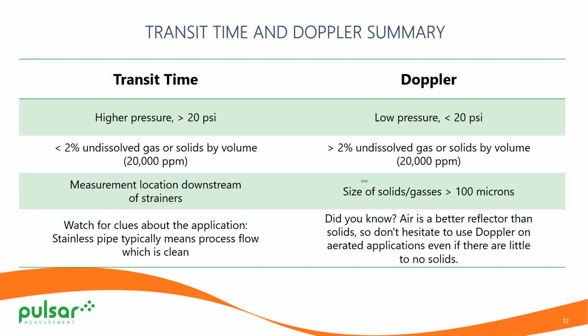Here's the way to diagnose this, and let me point something else out too. Sometimes we don't always get the most accurate information on the internal pipe diameter, or the customer might say it's not lined when really there is a lining in there. Then you can move the transducers around until you get that signal strength. It makes it a little more difficult, but if we get all the information up front and you measure correctly, use the spacer bar or a tape measure, generally you're going to get good signal strength right off the bat. So I hope that answers your question.